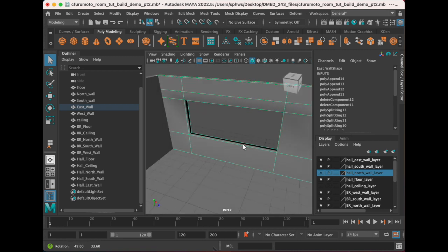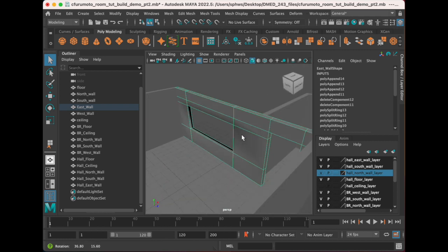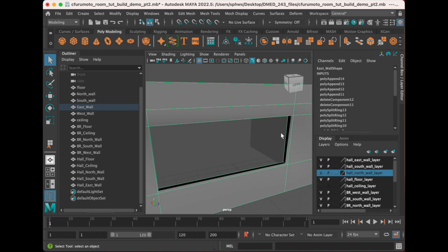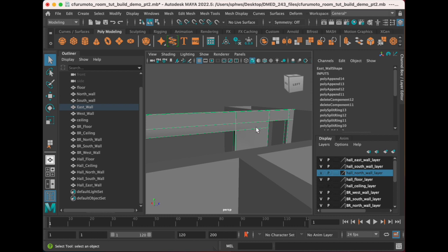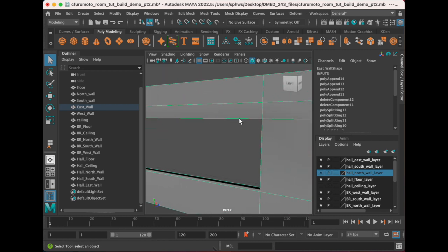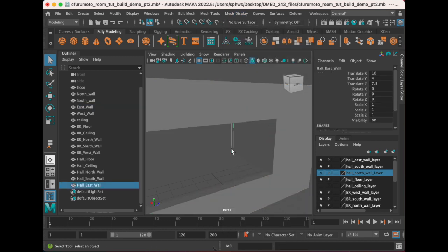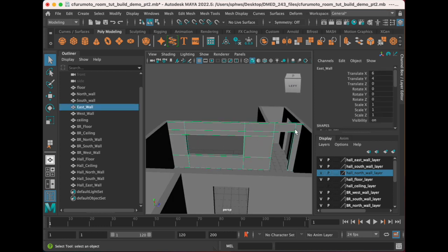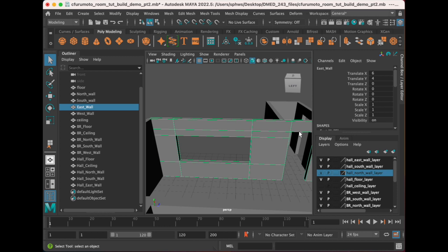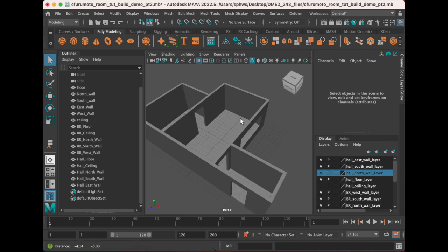Once again, you'll notice that wall can support multiple inserted edges. So these edges over here, don't delete them, please make sure you do keep those there. They add support, so you want to leave those even though you're not going to see them. If I go Harden Edge, once I click outside, you're not going to see those edges anymore, but they are important because they are holding the visual integrity of that particular wall. All right, but that should just about do it.